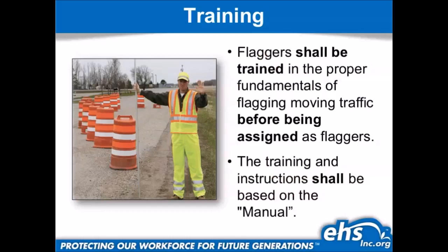Again, there are certain requirements for the flaggers. All flaggers have to be trained. All flaggers have to know how to move and guide people safely through these work sites. So yes, the state says they have to be trained, and the training has to be based on the manual, because I've been through different work sites and I've done recommendations for cities, because I'm out there with these guys doing the work, and I'll see that sometimes guys get creative on their hand signals. So they'll make a fist, like an equipment operator. Sometimes you'll see that they say stop by closing their hand, making a fist. Yes, an equipment operator will know that that means stop, but again, not everybody driving past your site understands that that's a stop sign, right?